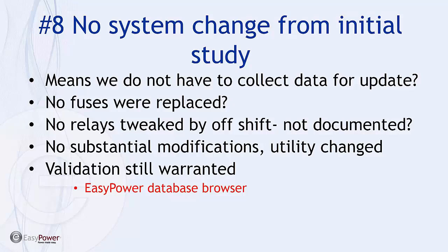And so consequently, I think we're missing the point of doing an arc flash study, because there are ways to, I think, spot check the critical. If the cabling hasn't been changed, the equipment hasn't been changed, I understand that there may not be a need to do a complete ground-up data collection. But frankly, what we're talking about is validation, and there's some key areas that need to be double-checked, and this will essentially vary based upon my specific case or situation.